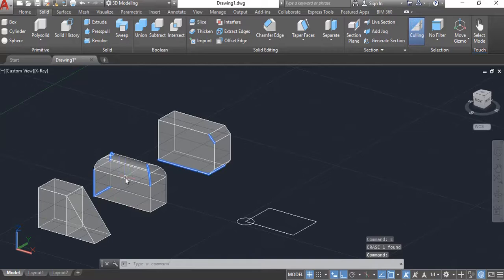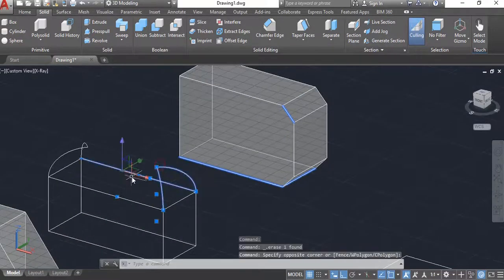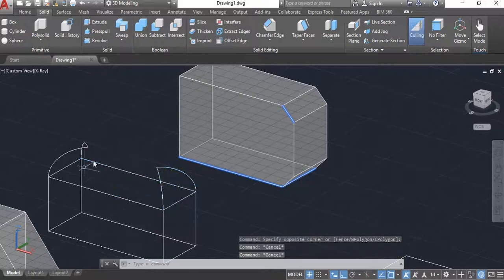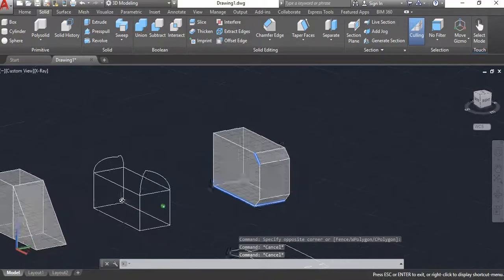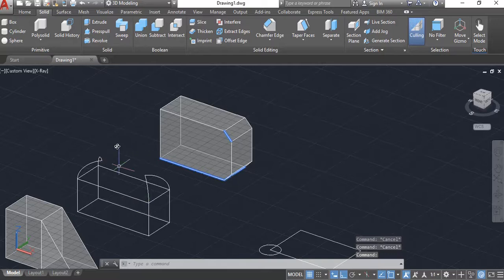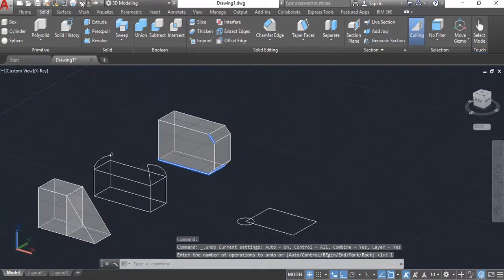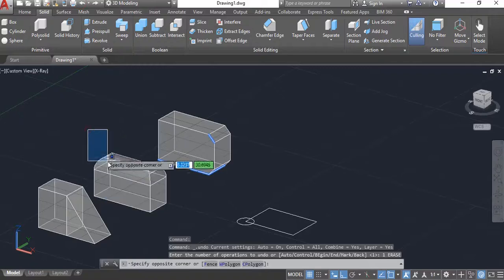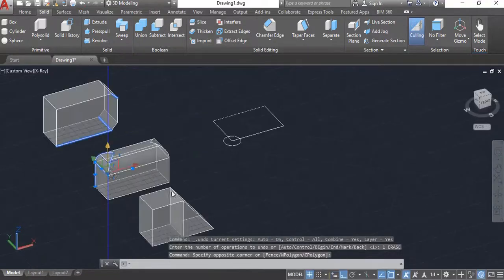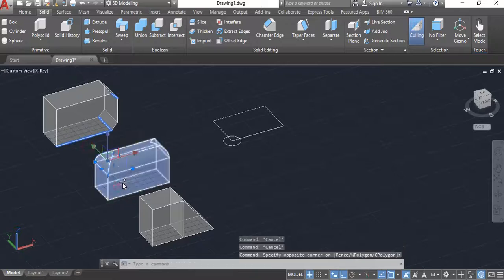Let's say I want to take this and find the wire frame. So I want to get all of these lines drawn in 3D, but I want all the edges to be single lines. I could go extract edges and select my item there. And now if I delete out that solid, it has all of my edges, except for apparently this one going across because it was rounded there at the top. But all of the other edges it now has. So let me undo that. Okay, so notice here it leaves the lines in as well, single lines.